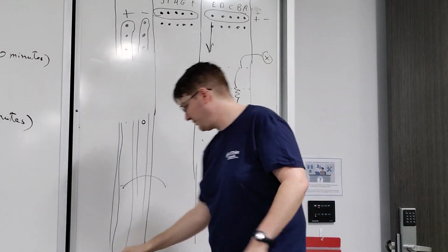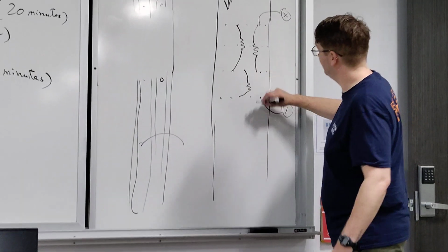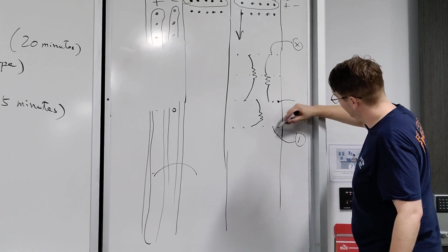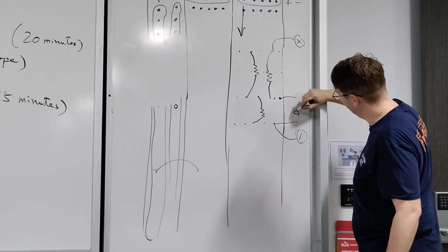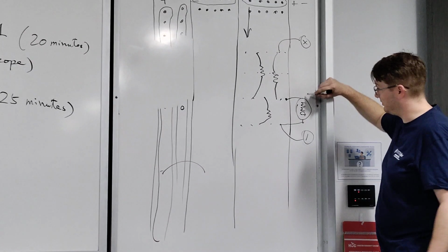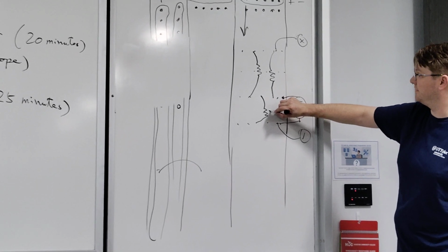So I just measured the voltage across one of these. Let's say I'm measuring the voltage across this one. I need my multimeter hooked up here and hooked up here. I'm going to call it a DMM, because that's what I'm used to, digital multimeter. And that's how I'm going to measure voltage across this resistor here.